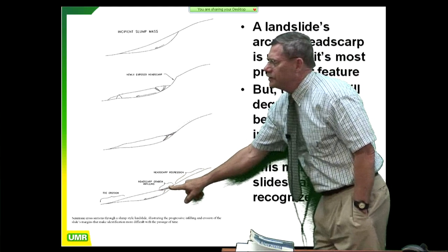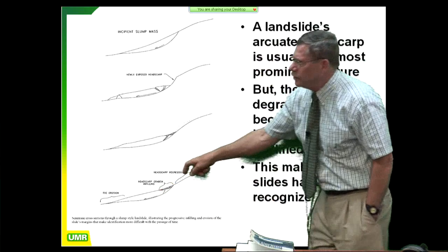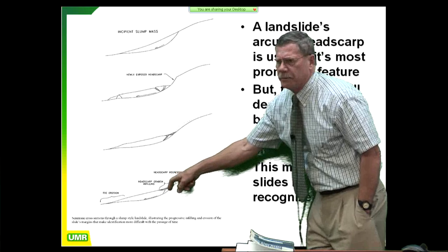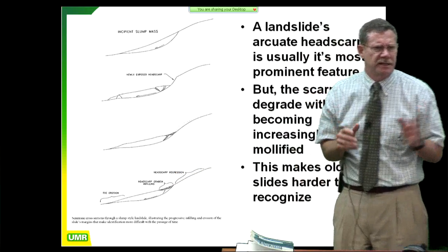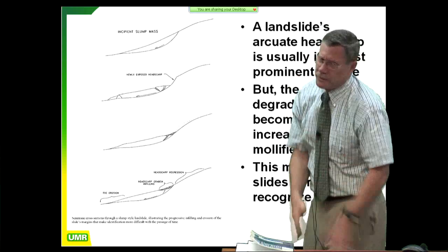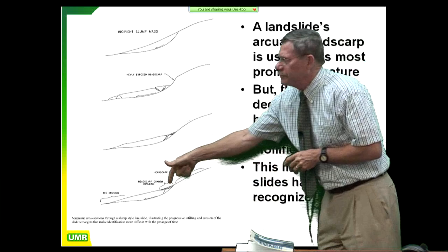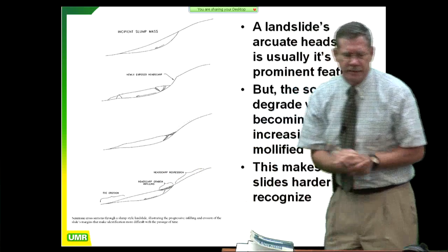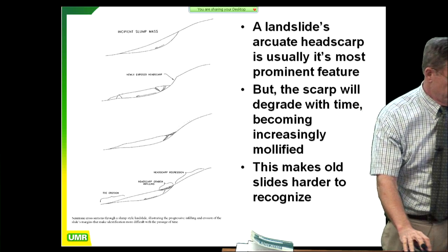And that's where everybody wants to build their house, by the way, right on that little bench right there, right at the head scarp. And when you do a perk test right here, you get wonderful percolation. Head scarp of a landslide perks like crazy. As much water as you pour in goes right down in it. Wonderful place to build a house. LA, that's where they like putting the houses, right there in the head scarp. And that's good for us because it makes work for a lot of people in our profession.